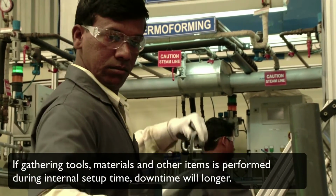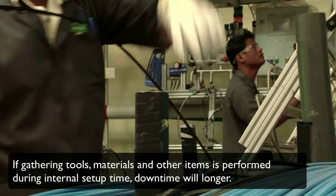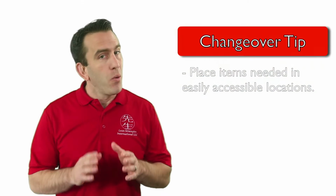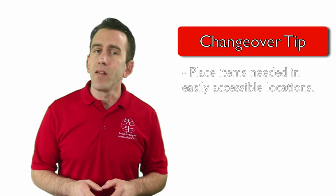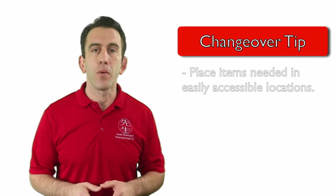If this is performed during the internal setup time, or the time when the machine is stopped, downtime will be much longer. With this in mind, any and all items needed for a changeover should be placed in a location that is easily accessible for the person performing the setup operation.